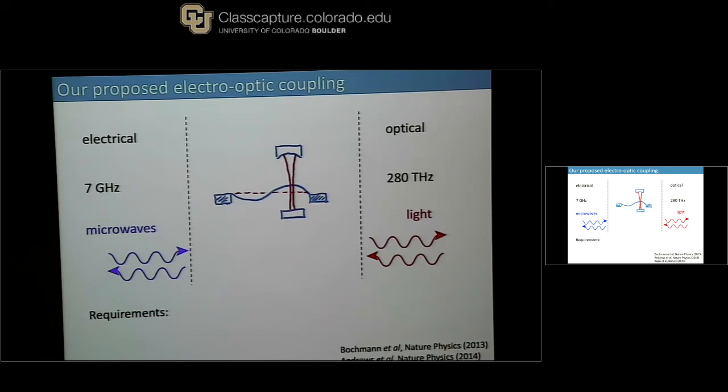All right, so what we can imagine doing, though, is we could also take one side of this mechanical element here, and we could put some metal on it, and we could make that part of a capacitor plate. So if we imagine that we then have a microwave system that is an LC circuit defined by a capacitance between those two green things and an inductance, where I have a really horrible inductor there. That's defined by some lumped element thing that's going to exist on some circuit board.